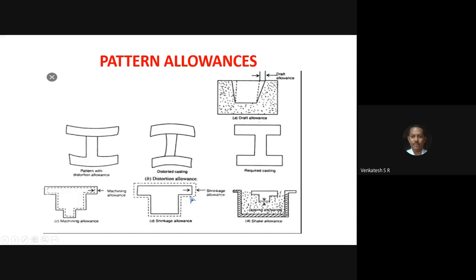Next, come to the point. Say, suppose you have the casting like this. You cannot remove the pattern as it is. Little tapping, little ramming is required on the pattern so that you can easily remove the pattern from the mold cavity.